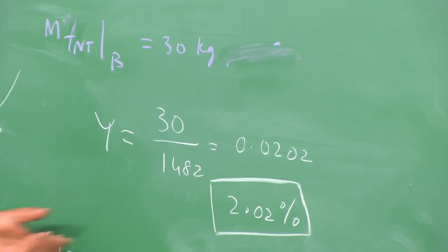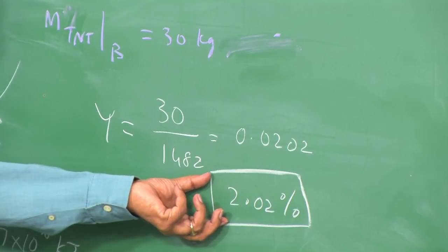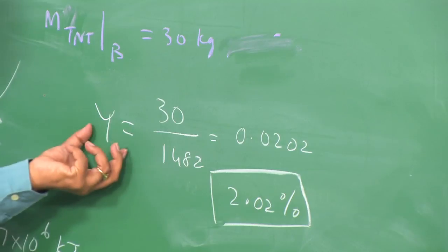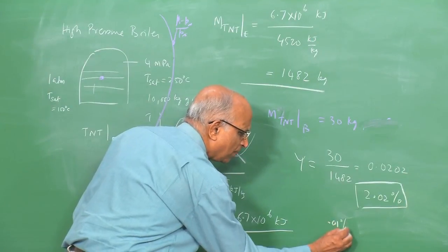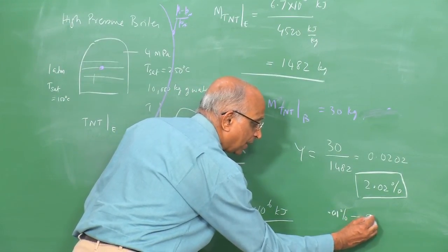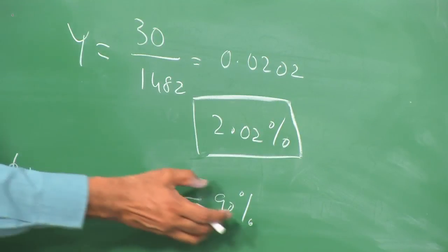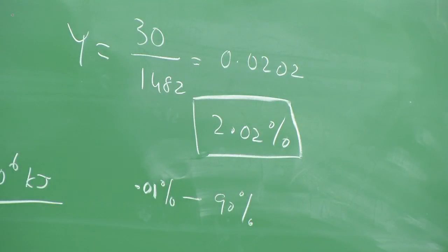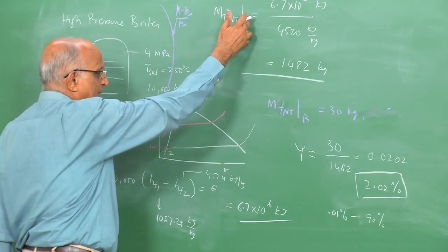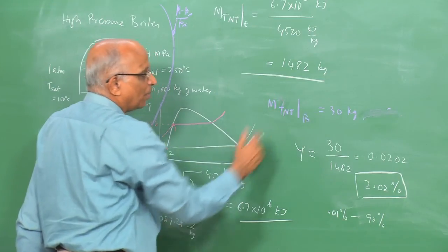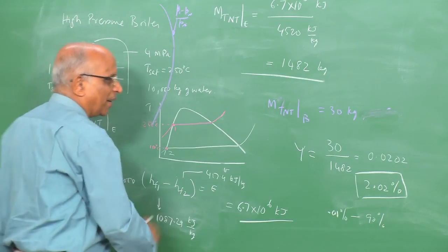In practice, whenever we have dust explosions or vapor cloud explosions, confined, unconfined, or any other form of explosion, the yield changes enormously. The yield could be as low as, say, 0.1% to as high as maybe 90%, or when I use very powerful solid explosives, the yield could even be greater than 100%. This is the way we calculate the yield, the TNT equivalence for the energy basis and the TNT equivalence for the blast basis. Let us do one last problem such that we are absolutely clear.